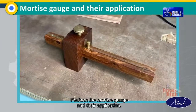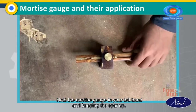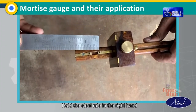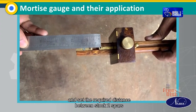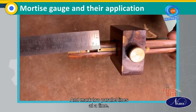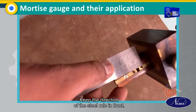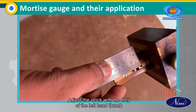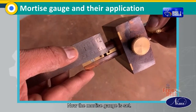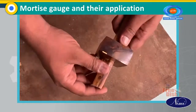Task 2. Perform the mortise gauge and its application. Hold the mortise gauge in your left hand, keeping the spur up. Hold the steel rule in the right hand and set the required distance between stock and spurs. Two spurs can be spaced at different distances and mark two parallel lines at a time. Keep the direction of the steel rule in front. Adjust the stock with the help of the left hand thumb and index finger. Now the mortise gauge is set. Tighten the thumb screw to fix it in place.